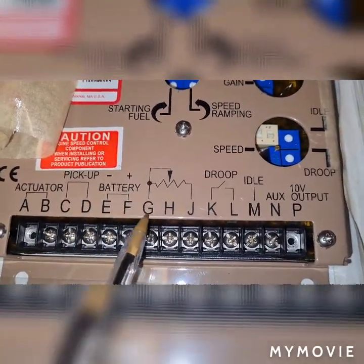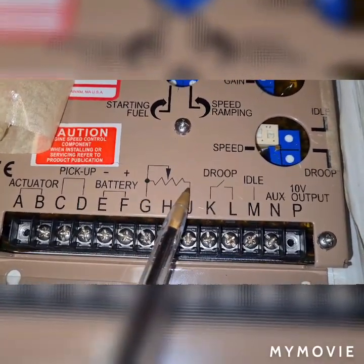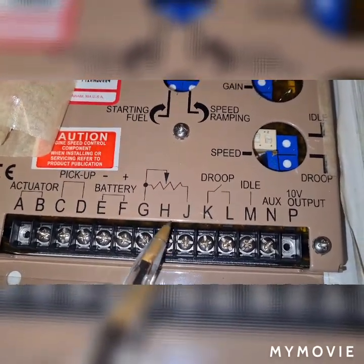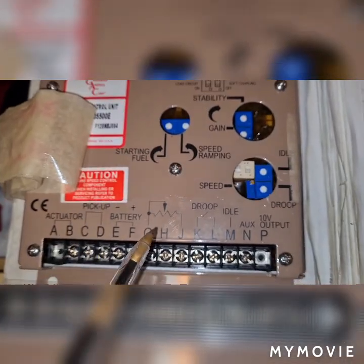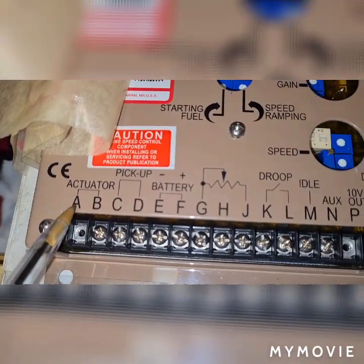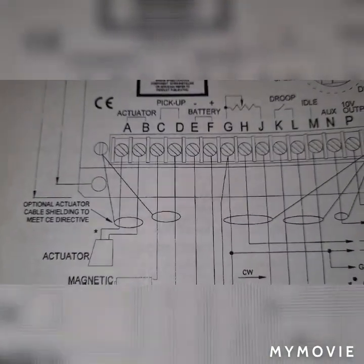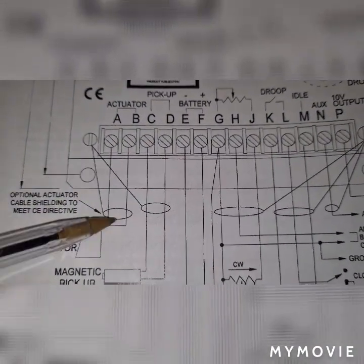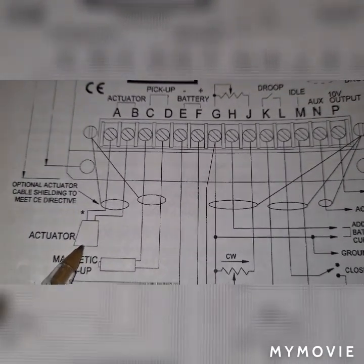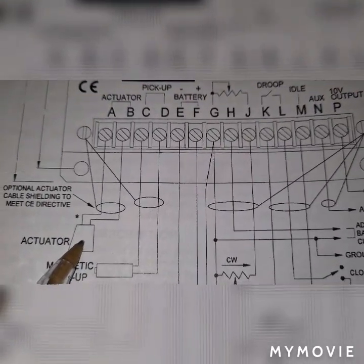Once you have terminal G and J connected together with a 5 kilo ohm resistor, you may have 2400 Hz, and this signal is processed by the speed regulator to give an equivalent voltage output on our actuator. This is the actuator A and B connection, going directly to our actuator. This actuator normally has an operating voltage from 2 volts, 4 volts, 7 volts up to 24 volts, depending on the speed that your engine may require.